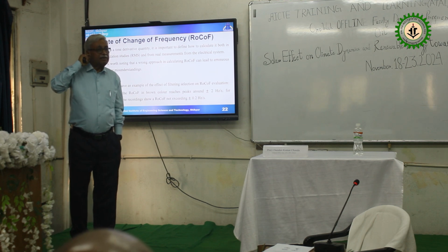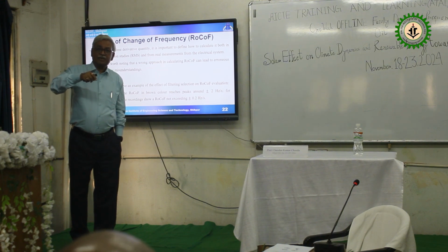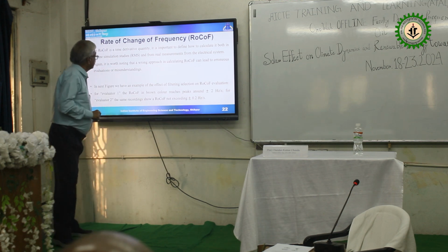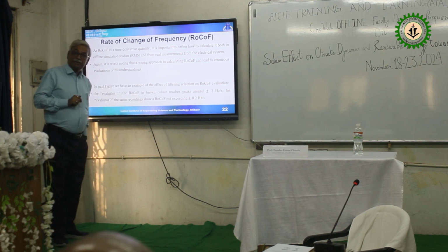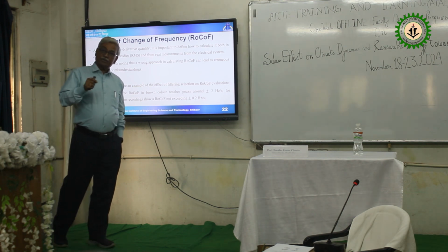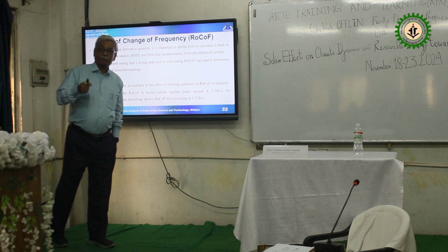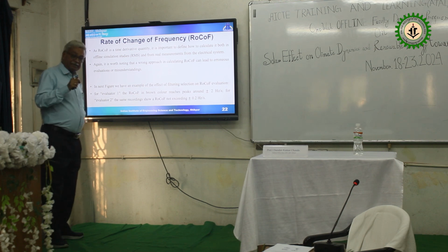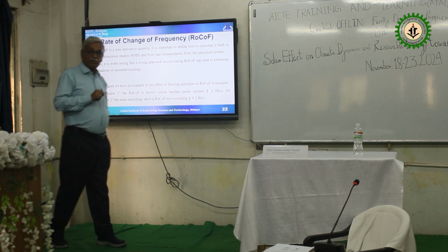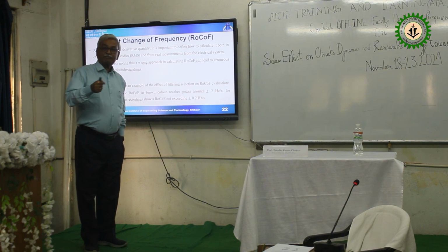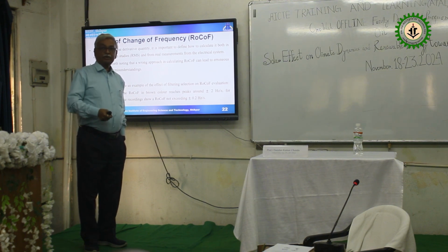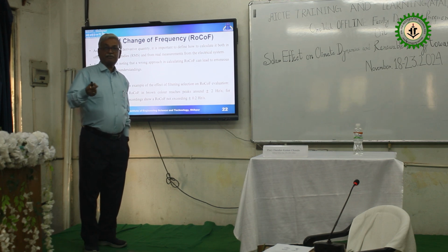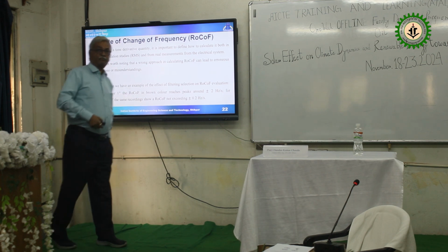Have you ever heard this term, frequency nadir, where the disturbance occurs at the time of disturbance? Have you ever heard of it in AGC, automatic generation control, with renewable energy? So we can calculate the frequency nadir point, and we are able to calculate the RoCoF. And that is the theme for the power electronics people. They will give the estimation of the inertia after penetrating the renewable energy, and the power electronics will provide the frequency response, so that within a few milliseconds they have to take care of the frequency.